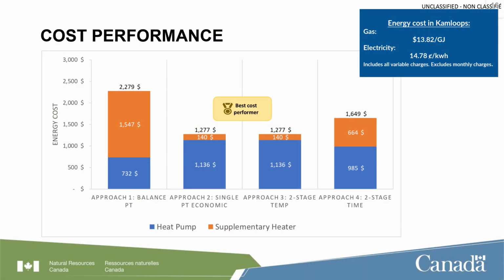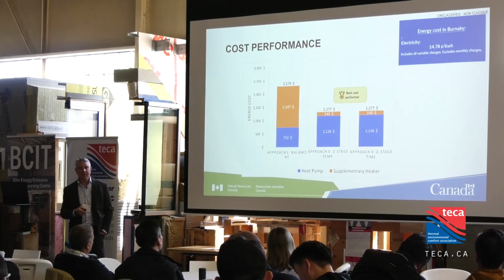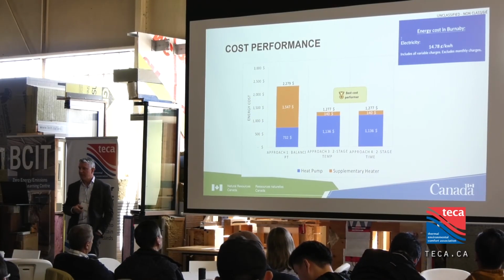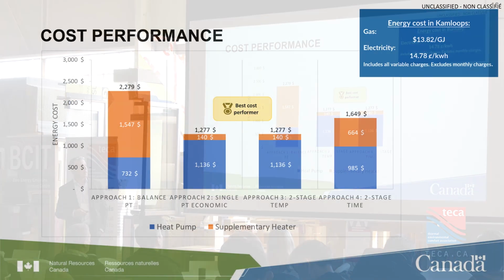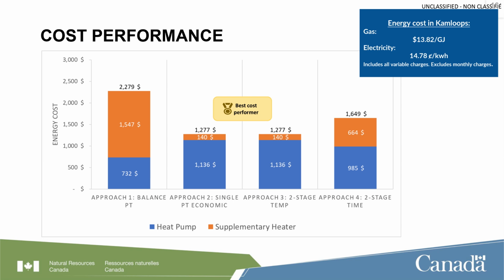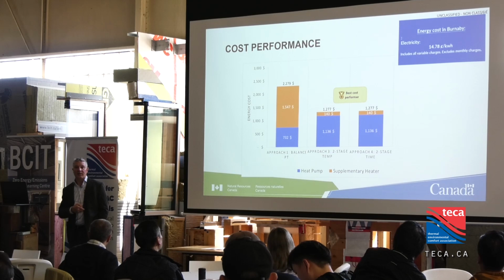But in this case here, probably won't have too much of an impact because we're not really dealing with a dual fuel system. So when it comes to cost performance, our approach number 3, which is our 2-stage temperature-driven balance point transfer of supplementary heat, as well as the approach number 4, the 2-stage time, they came in pretty well almost exactly the same. Okay, so that was much better than going with the standard balance point switchover.